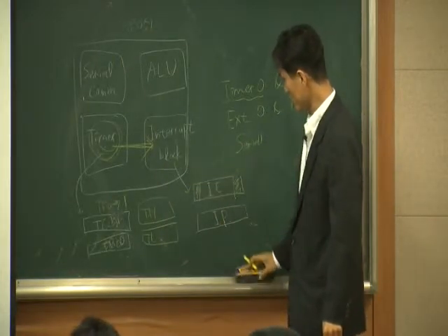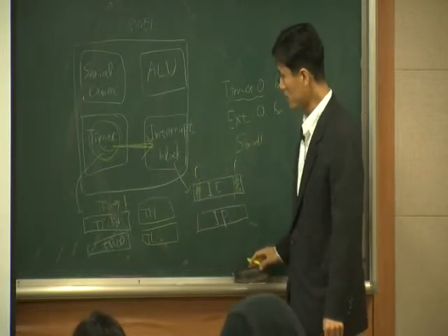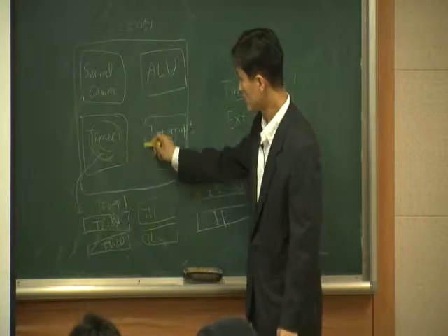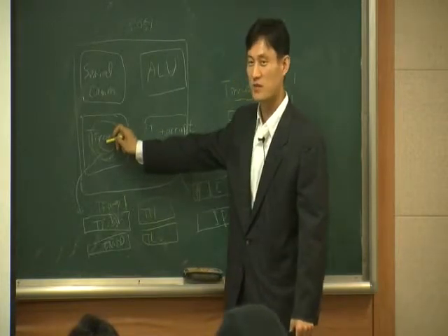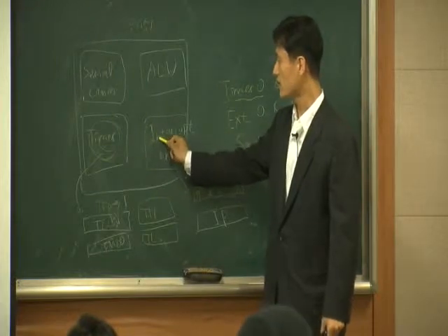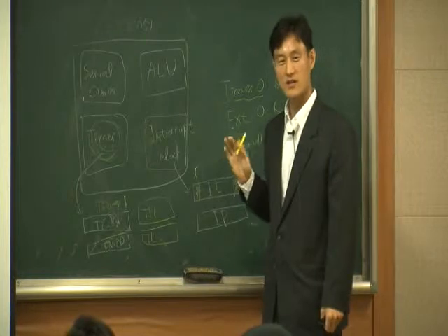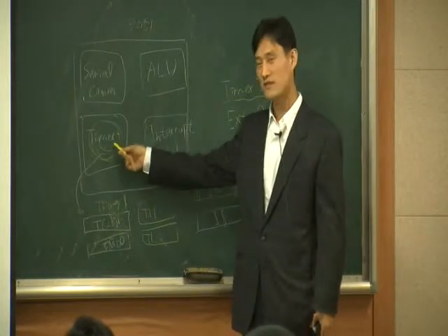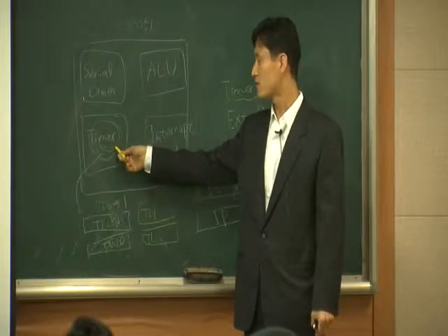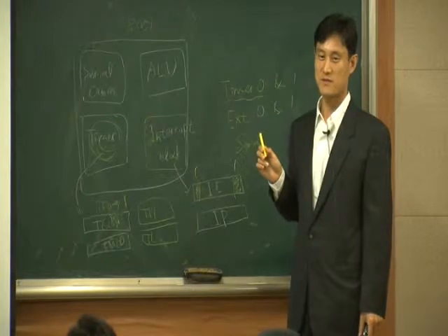And putting it another way, you enable the interrupt block, but you forgot to program the timer. Okay? You didn't do anything on the timer. In that case, this block is ready to get an interrupt, but actually the event does not occur, right? Because you didn't configure the timer, so the timer does not run. So the timer interrupt never happens.